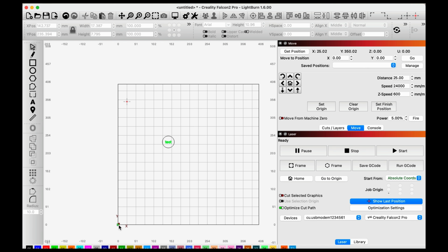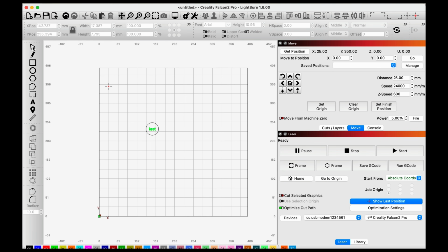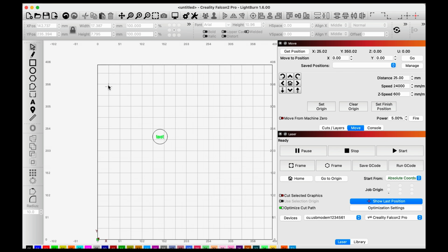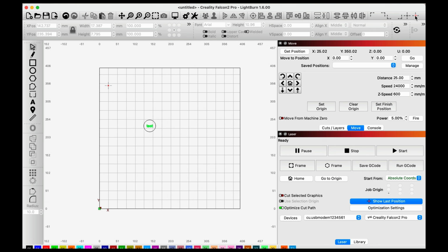The absolute is probably the easiest to understand because the artboard basically is the work area. So right down here at the bottom is our 0, 0 position. So that would be our far left corner. And it's also kind of handy because you're usually gonna get a live readout of where the laser head is. So you can see this crosshair right here is where our laser head is. And one kind of fun tool that you have over here on this panel that isn't an art creation tool, but really a movement tool, is your set laser position. So this little nav thing on a map.